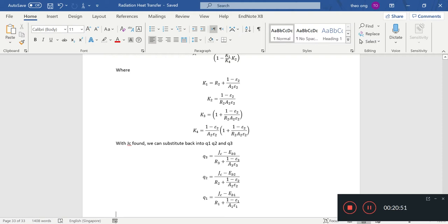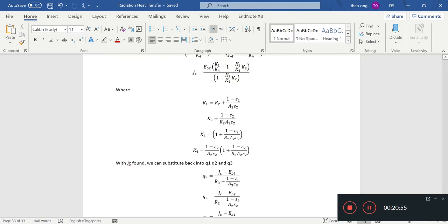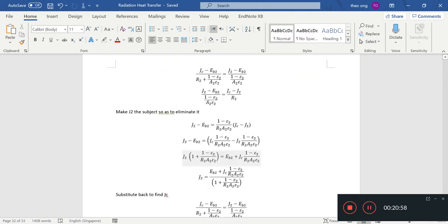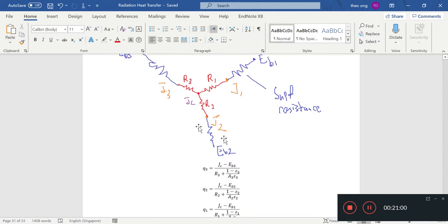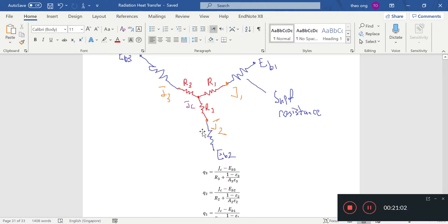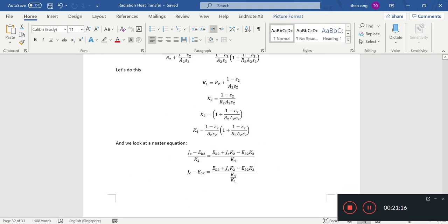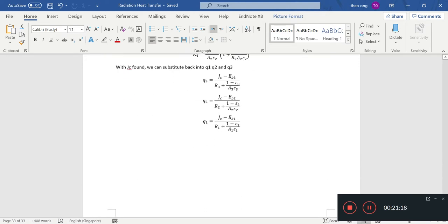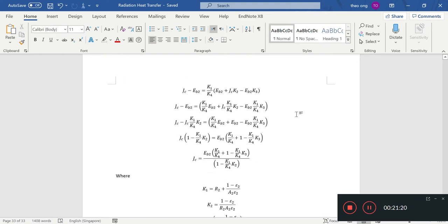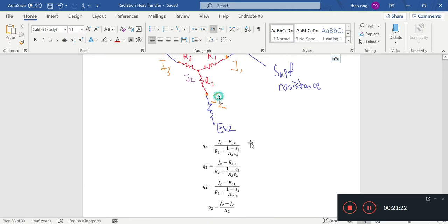Alright, so it's a lot of manipulations, copy and paste. Though of course, it can get pretty messy, and you should know this only applies to diffuse gray boundaries without any kind of external radiation in. And of course, you must know the surface resistance and the view factors, otherwise this analysis becomes a bit useless. But this is just to give a flavor of this electrical network analogy.